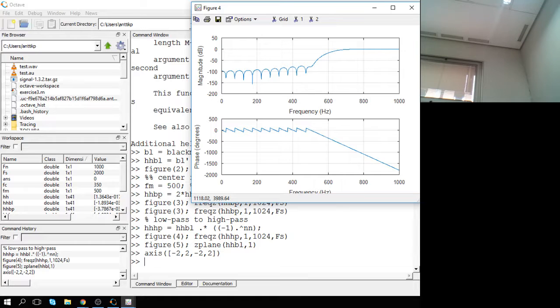The mid-range control basically is the volume control. So you have 3 bands. On a digital filter: from 0 to 200 hertz, from 200 to 2 kilohertz, from 2 kilohertz to, well, the Nyquist rate. So you would need a low-pass filter, bandpass filter, and high-pass filter.